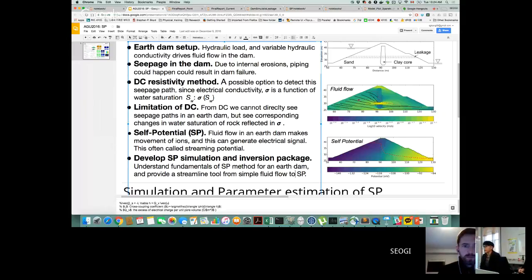But it's not necessarily wrong, though. It's not telling you the amount of water. It's just telling you that if there was water, it would flow faster. Right. So here I think what I did is I solved this full domain and computed the pressure. Actually, I solved for hydraulic head, and then you can compute the pressure by subtracting the height. Then you find the zero contour. So I'm assuming above this one it's zero pressure, meaning there's nothing happening. That's not quite right.